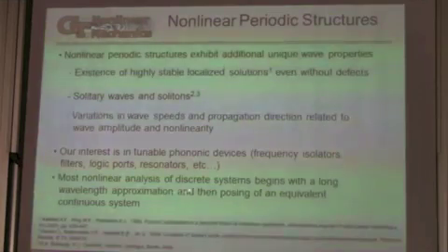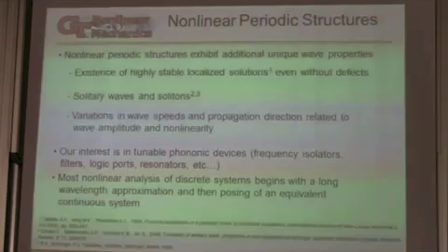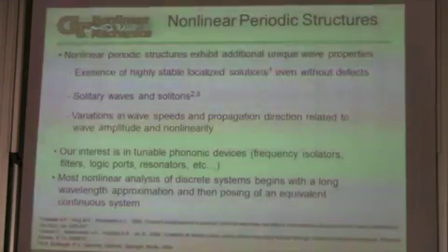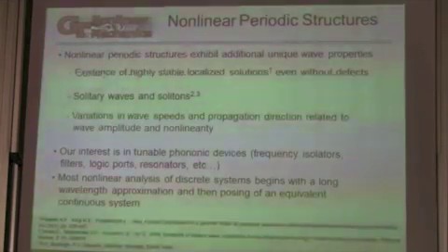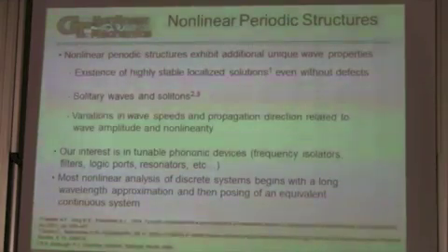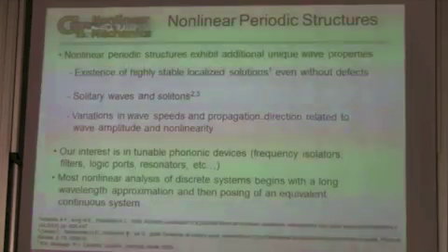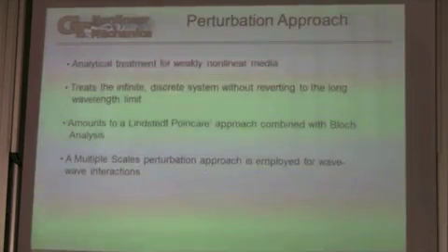And our focus is really on the discrete. This is where I can't really argue with Francesco. We like to work with systems that are discrete, and phononic crystals can very much be discrete, especially at the MEMS level. You can have stiffness-like elements, you can have mass-like elements. But we work with a discrete system, and therefore we don't have to invoke a long wavelength approximation. All right? That's typically what's done with an equivalent continuous system, to go into continuum mechanics, maybe work with a KdV or Burgers' equation.